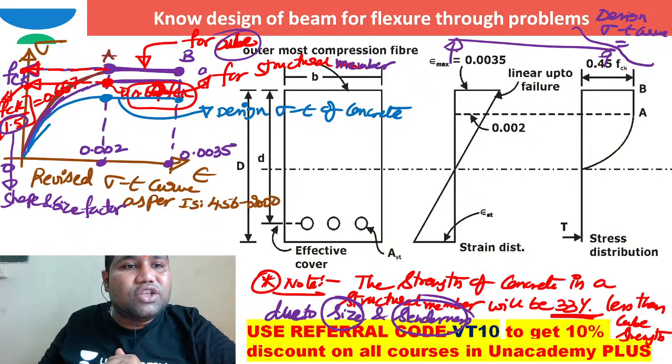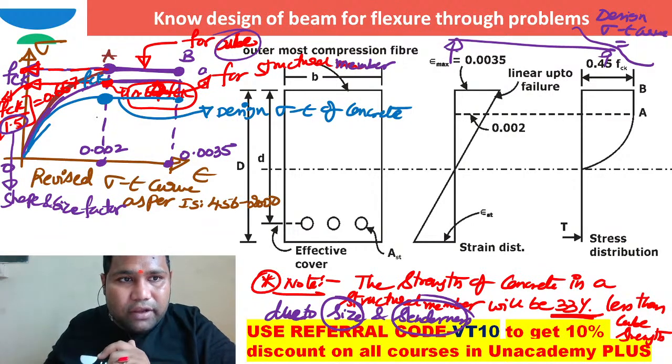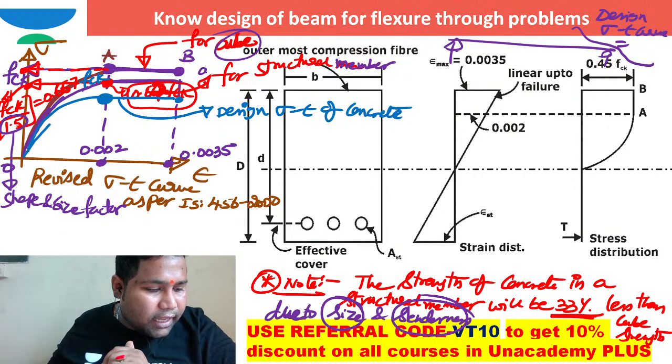Already the strength for the structural member is 0.667 FCK. After I do this, how can I get the design strength of concrete? The actual strength of the structural member divided by the factor of safety for concrete. So what is the factor of safety for concrete? The factor of safety for concrete in limit state of flexure is already 1.5. So I can write it directly here.